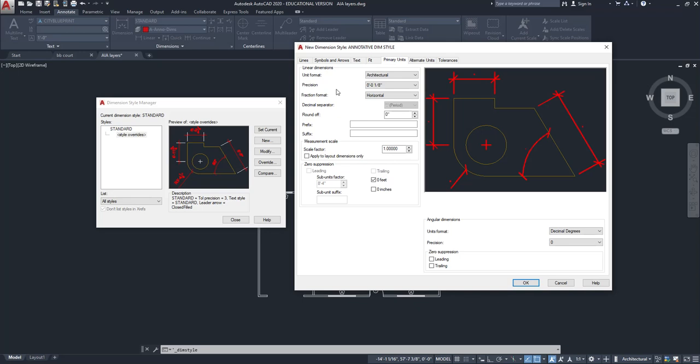Okay. Very rarely on a floor plan will you see an 1/8 of an inch dimension because a carpenter or a drywaller, they'll be very, very close, of course, but an 1/8 of an inch is a pretty tall order for that kind of thing, right? It needs to be 25 feet and 1/8 of an inch, and I'm going to measure it, right? Not very realistic, of course. I think that a more realistic precision here would be 1/4 of an inch. And probably even more realistic than that would be 1/2 inch or to the whole inch, but we'll just put it at 1/4 of an inch. So this will be the lowest increment that your dimension will read to, okay?